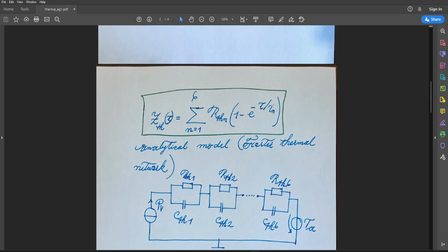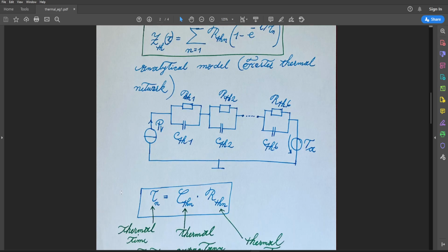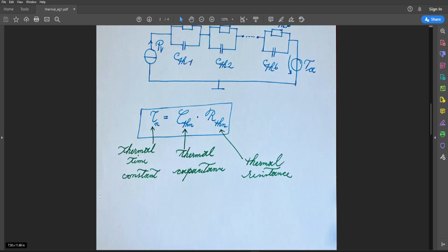These are normally also given by the manufacturers, but in the chain form or the circuit diagram of this model is represented somewhat with Rth and Cth pairs. That means for the circuit representation we need to transform the time domain of the model to the capacitance values here. To do that, we can use the relationship of thermal time constants here.